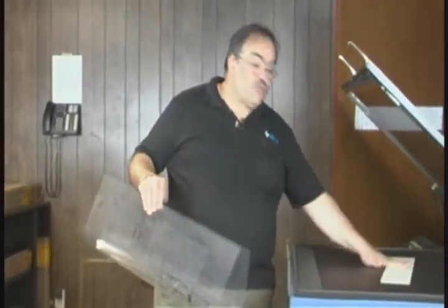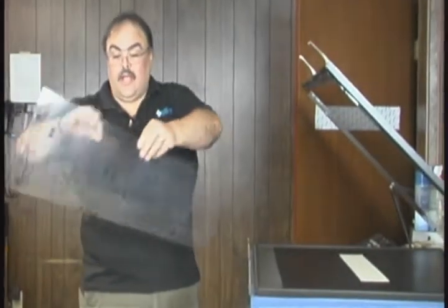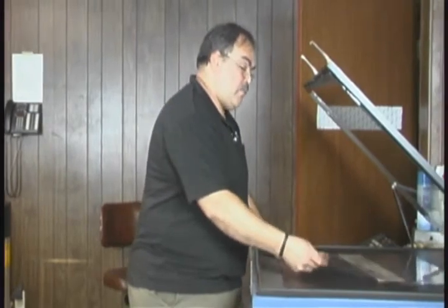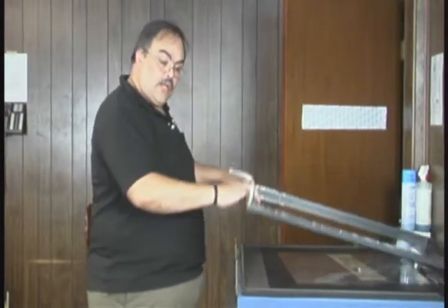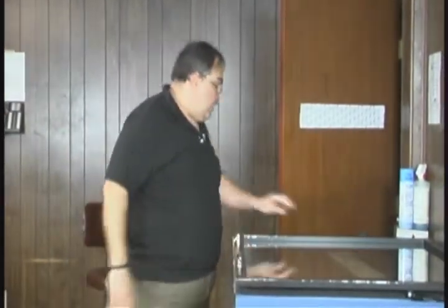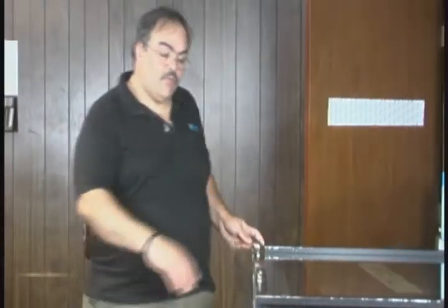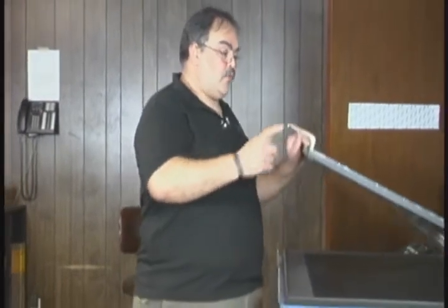We will place the emulsion side up, and we will match the artwork emulsion side down on top of the paper. We'll close the contact printer, and then we will draw vacuum on it, and after the machine draws vacuum, we'll do a 1.5 second exposure. After that exposure is done, we will turn off the contact printer and proceed to move the paper to our film process.